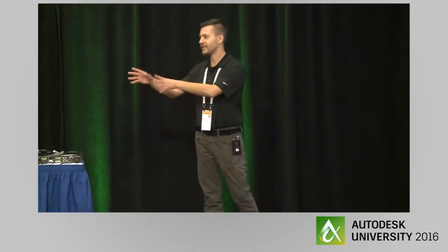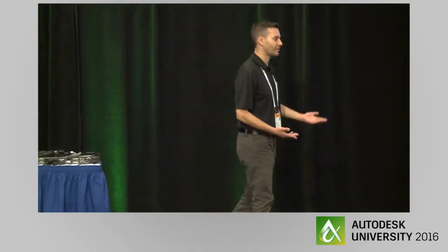So I was using an RTE file, the Revit template. It was referenced this morning as well. Why not use a Revit project as your template? Because I can load in everything that I've done here into my Revit project, plus a few other things, like work sets. So if you're work sharing, that's something to consider. If you're not, then RTE might be a lighter way to go. It just depends. But that's a great point.